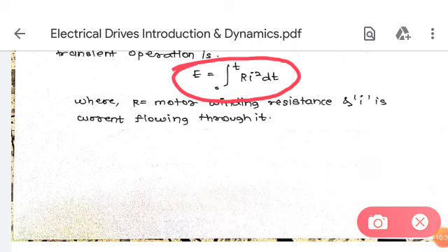So therefore we limit the current of the motor to twice or 1.5 times the rated, and then we design the starter according to it. Then we start and operate the motor, and in that case the motor will not burn. The same case is there for stopping the motor using electrical braking methods, as well as reducing or increasing the speed if the acceleration is very high. In that case huge losses will occur in the motor windings, and they may damage the motor windings.